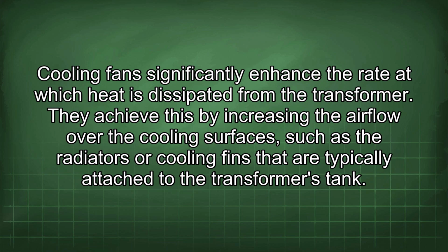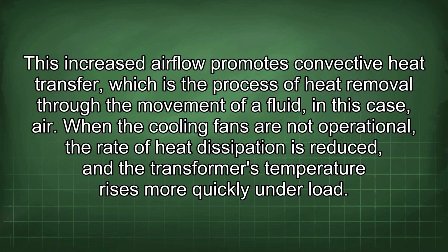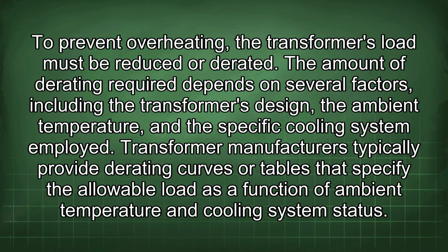Cooling fans significantly enhance the rate at which heat is dissipated from the transformer. They achieve this by increasing the airflow over the cooling surfaces, such as the radiators or cooling fins that are typically attached to the transformer's tank. This increased airflow promotes convective heat transfer, which is the process of heat removal through the movement of a fluid, in this case air. When the cooling fans are not operational, the rate of heat dissipation is reduced, and the transformer's temperature rises more quickly under load. To prevent overheating, the transformer's load must be reduced or derated.